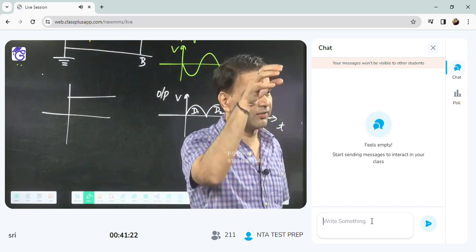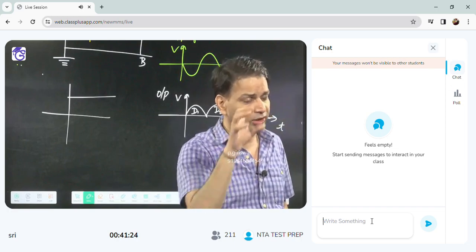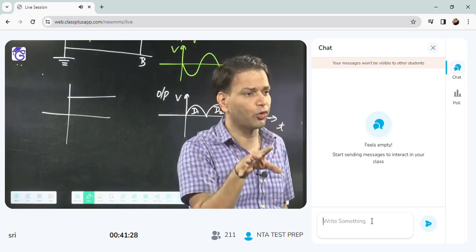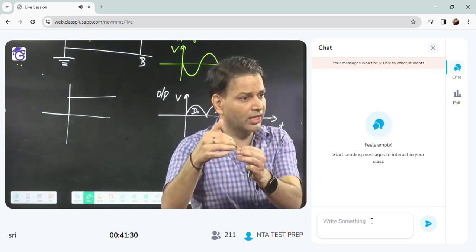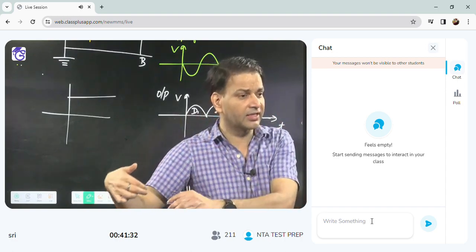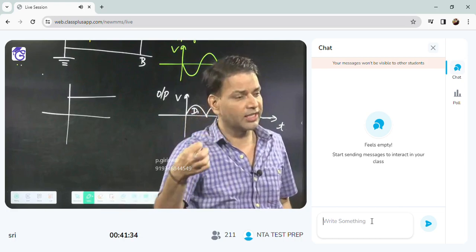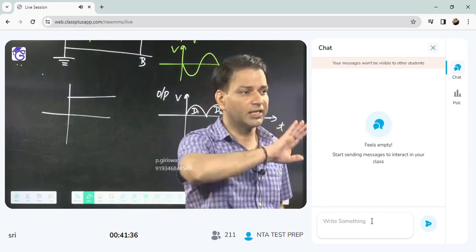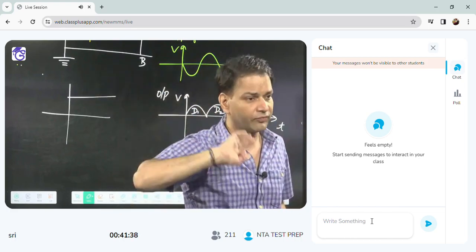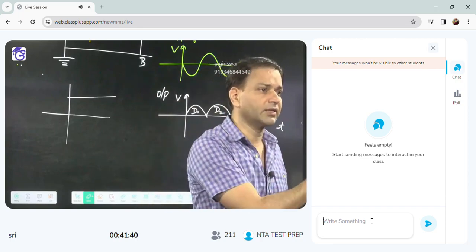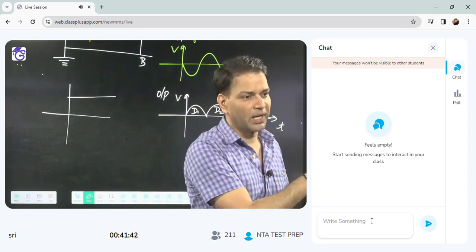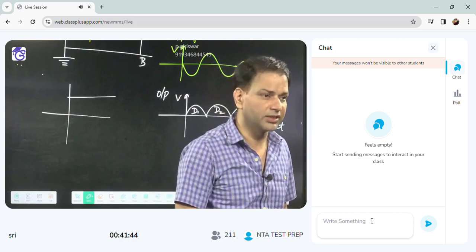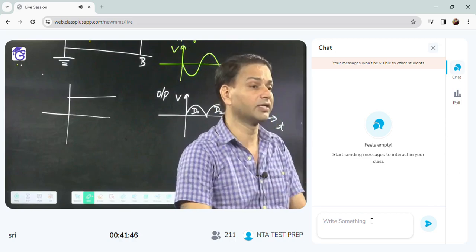So when I am using the inductor in series, DC will flow through the inductor, and the inductor is connected in series with the load. So the load will get the DC, and the AC ripples will get filtered out. That's why we are connecting the capacitor in parallel, or we are connecting the inductor in series. That is a filtration or filter circuit.